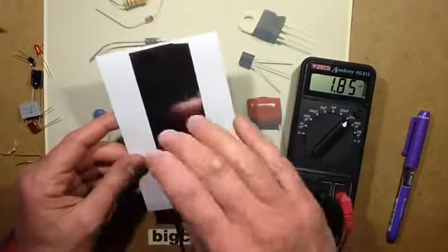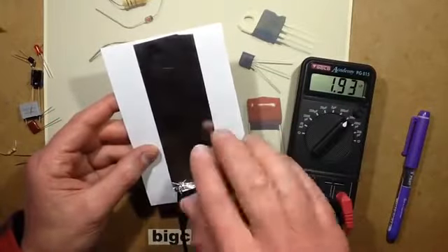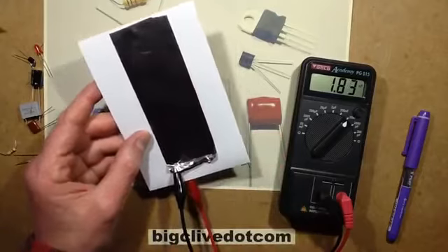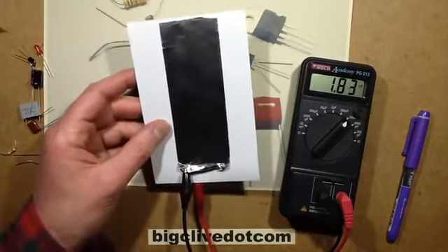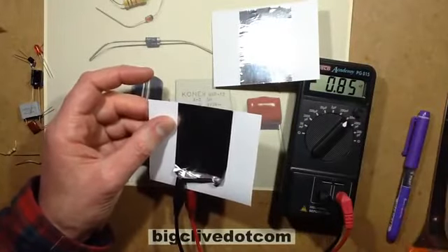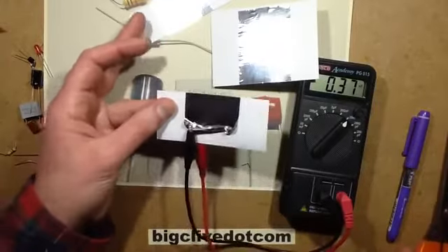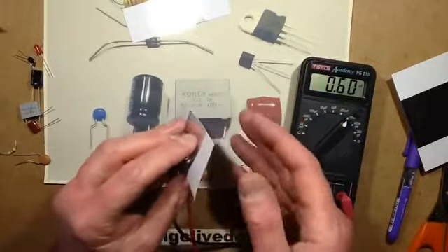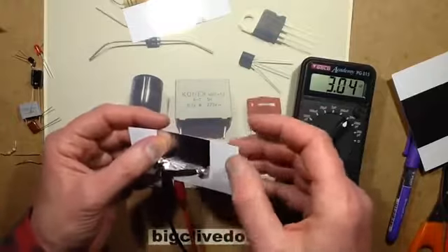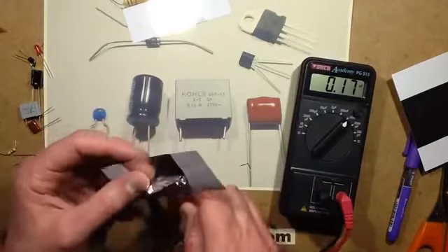And to prove that the area of the foil affects the capacitance, if I get a pair of scissors and cut this in half right now, it's 1.83. If I cut that in half, it's half the capacitance. It's now 0.8. And if I cut that again in half, it'll go down to about 0.4, which it has. So that's basically how a capacitor works. It's basically an insulator, the 2 metal plates on either side, and the area of the metallization and the thinness of the separator is what determines the capacitance.